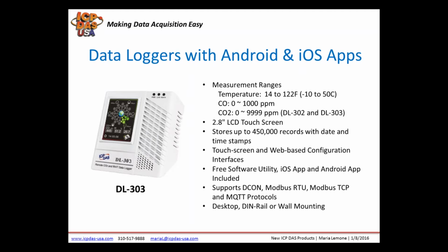It has RS-485 and Ethernet ports on board. It can be powered over Ethernet or with a 10 to 30 VDC power supply. It integrates easily with HMI and SCADA systems. It comes with an easy-to-use iOS and Android app for smartphone-based control and monitoring.